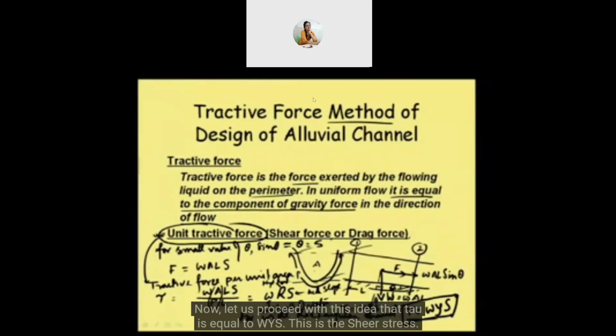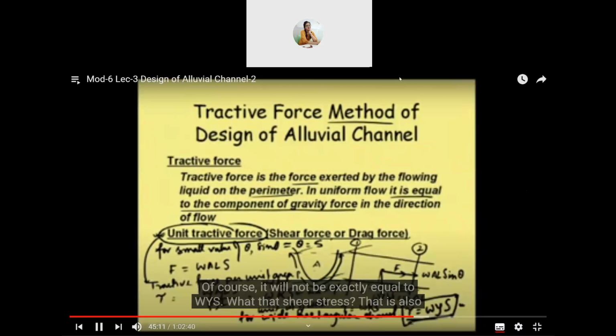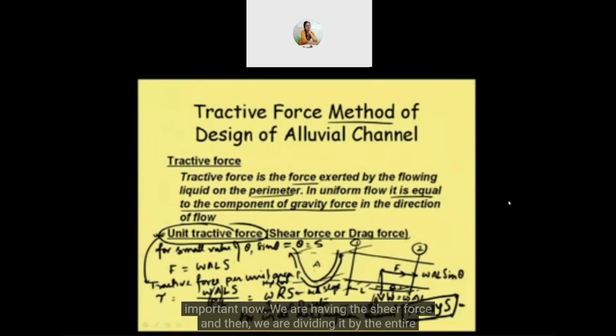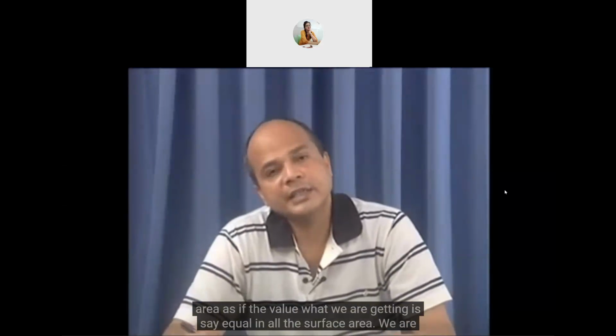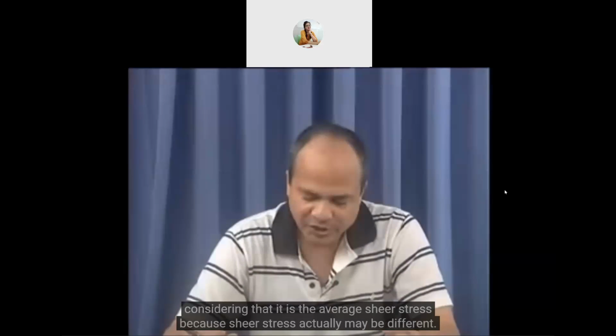Now let us proceed with this idea that tau is equal to WYS. This is the shear stress, though of course it will not be exactly equal to WYS. What that shear stress is, is also important. Now we have the shear force and we are dividing it by the entire area, as if the value we are getting is equal over all the surface area. That is, we are considering that it is the average shear stress, because the shear stress may actually be different.